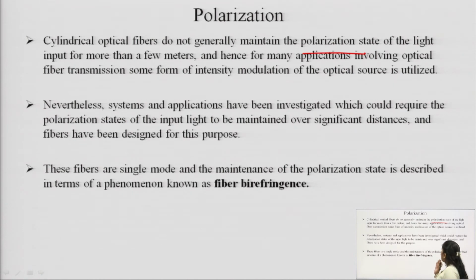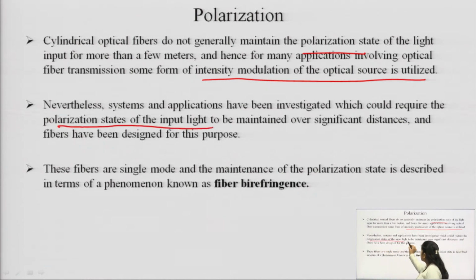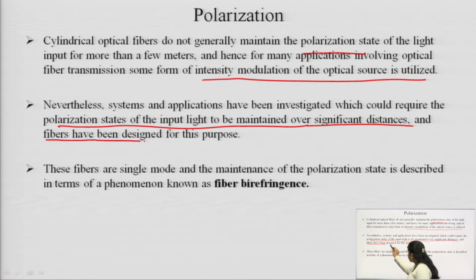In many applications involving optical fiber transmission, some form of intensity modulation of the optical source is utilized. Nevertheless, systems and applications have been investigated which could require the polarization state to be maintained over a significant distance, and thus the fiber has been designed for this purpose. But as all of us already know, the polarization state has to be maintained, which is not followed in the case of cylindrical fiber. So, for maintaining this polarization state, some sorts of fibers have been designed.